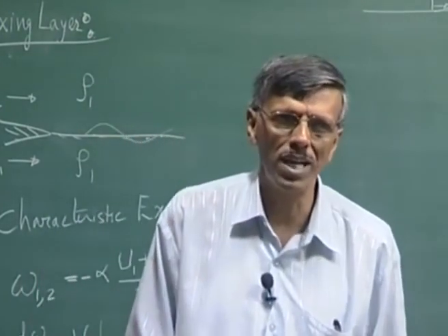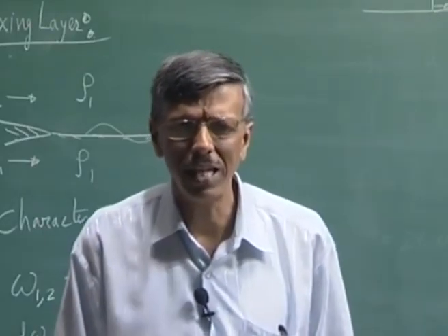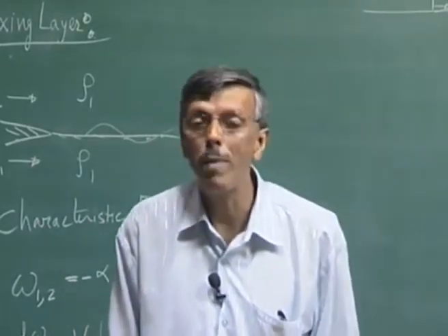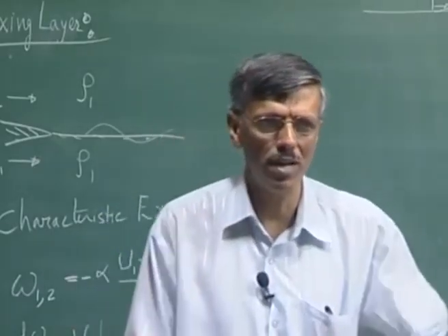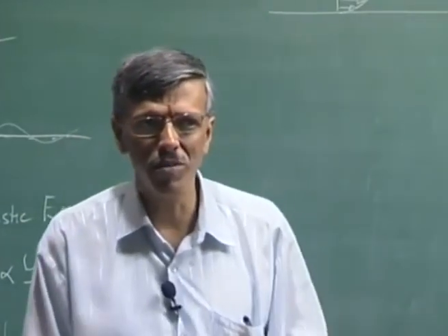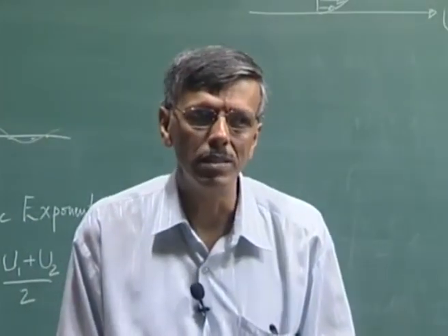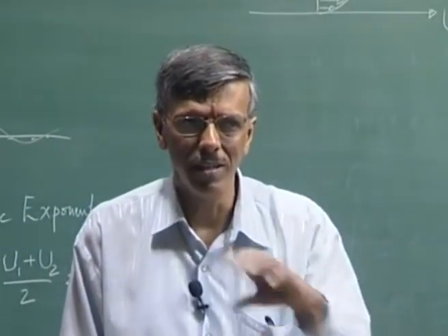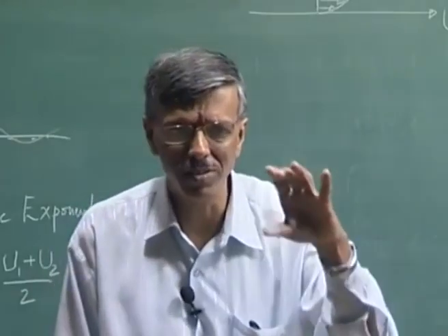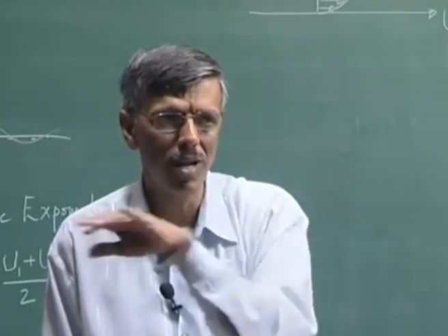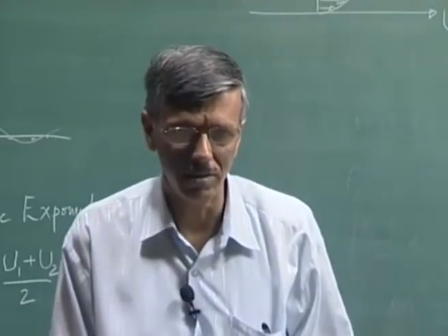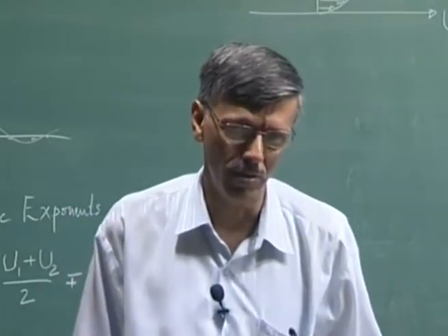So what kind of flow is that? That sort of flow is called a parallel flow. Why? Because everywhere it is the same. So if I try to think of a streamline, for the same height, at two different stations, it will be the same value, because it's only a function of y. So the streamlines happen to be parallel. That's why it is called a parallel flow.